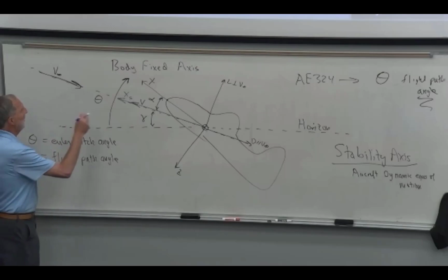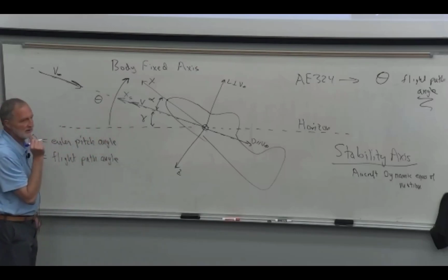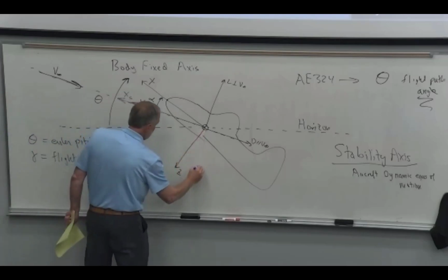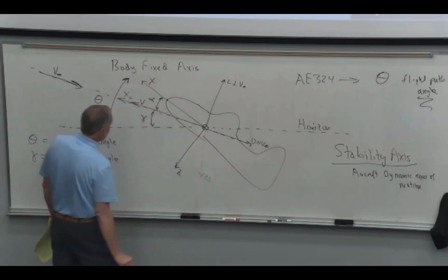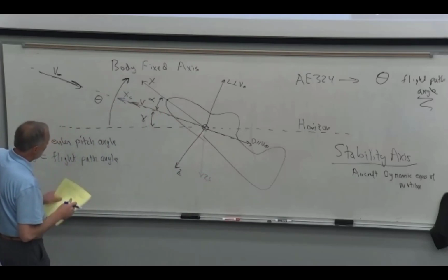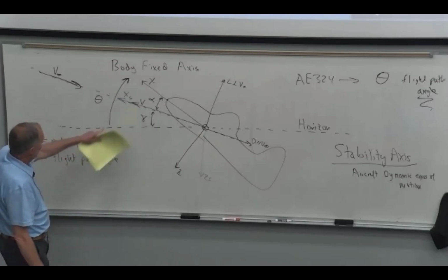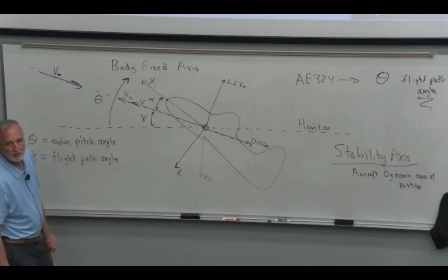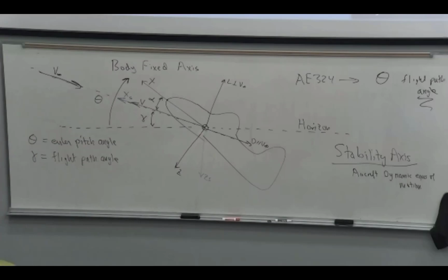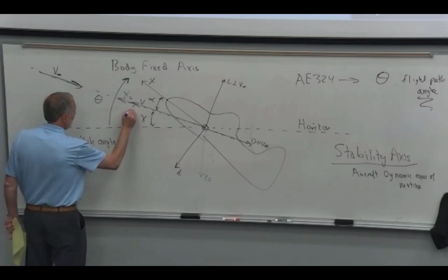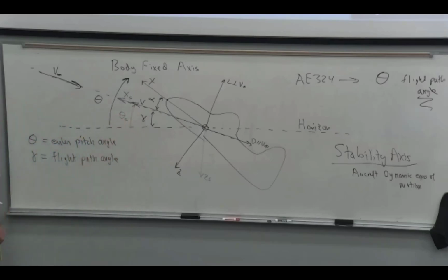So we're going to say, we're flying at 100 knots at an angle of attack of 5 degrees. That's the direction XS is. And then here is the Z axis angle here. And we use that, and that's the stability axis system. So what is the pitch angle, theta, of the stability axis system? Because remember, the Euler angles are just the rotations to get to that axis system up in the air. Well, it's just the angle there. Again, theta is the pitch angle up to the axis stuck on the airplane.